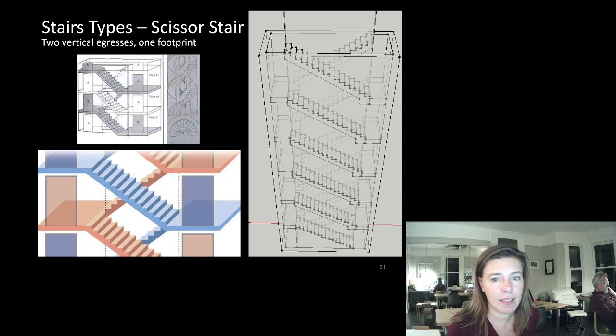You can normally tell if it's a concrete stair versus a steel stair. On a steel stair, if you do a heel drop, you'll feel the vibration more than on a concrete stair. When you do a heel drop on a concrete stair, you will feel very little.